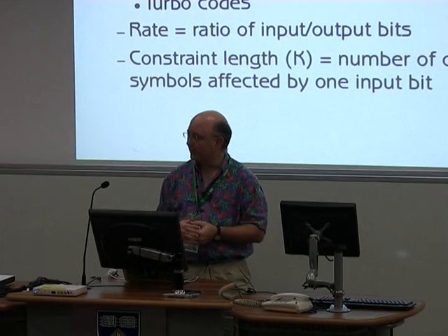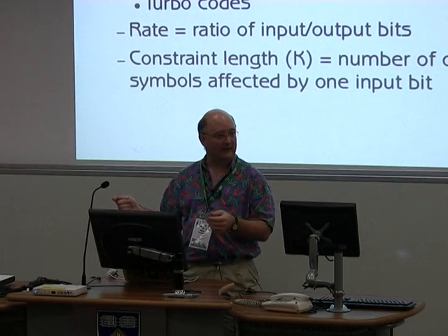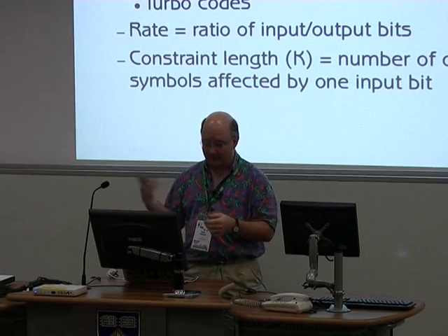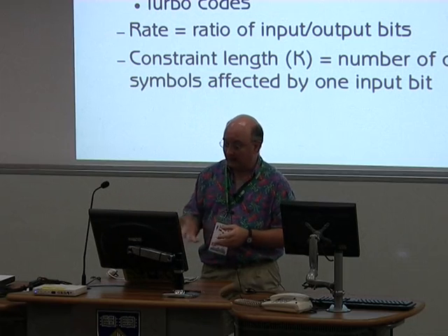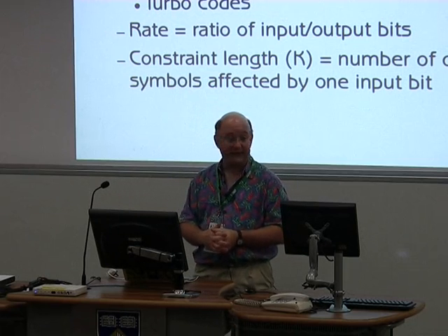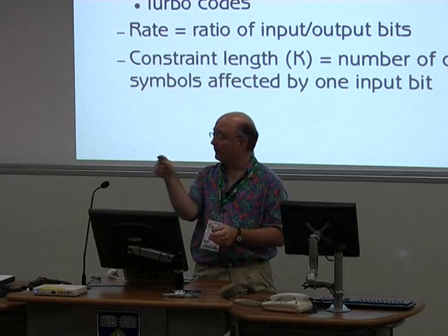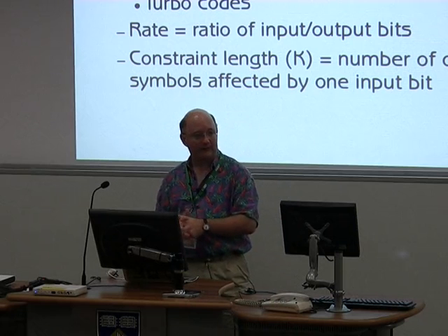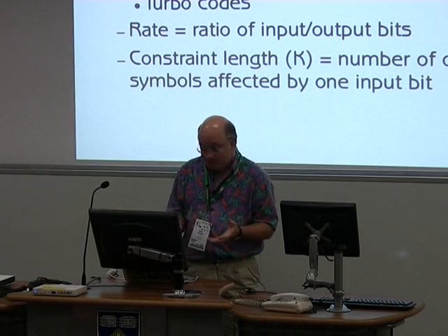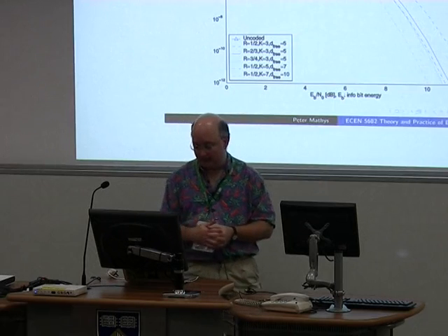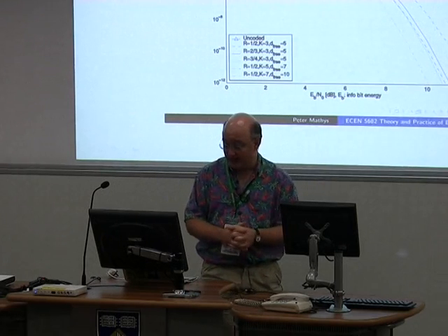So that's what the constraint length means. After that constraint length, a change in the input bits can have no effect on the output, because that's what the constraint says. Constraint length for non-recursive encoders is really easy to understand. You just look at the number of bits that are being put together. For recursive ones, it's a bunch more maths. I haven't quite figured out how those work. Someday, maybe. Maybe I'll have to implement one when I do turbo codes next.